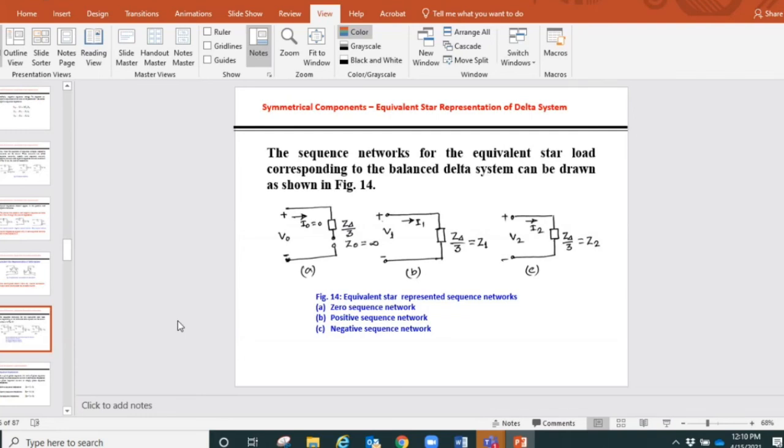If you keep the voltage of the generator constant, and Z is increased because of the increase in frequency, what will happen? Current will decrease. Yes. Then the next step is power. That is where Callum was talking about. What will happen to power? There'll be a decrease in power. Think about current, power, and when it comes to power, you will think about both active power and reactive power.